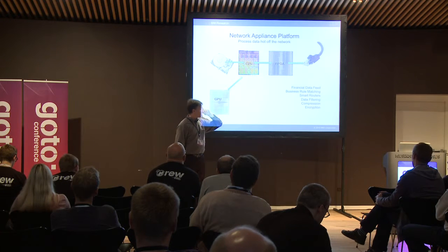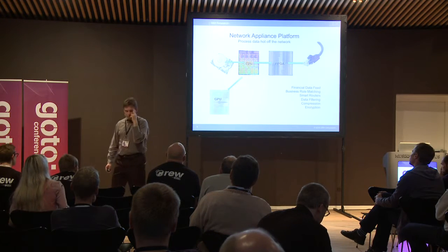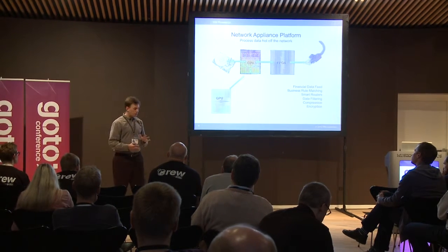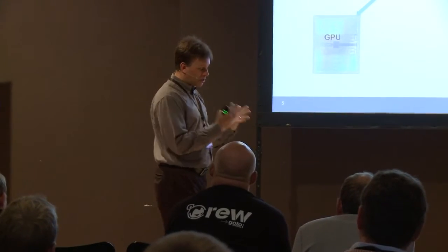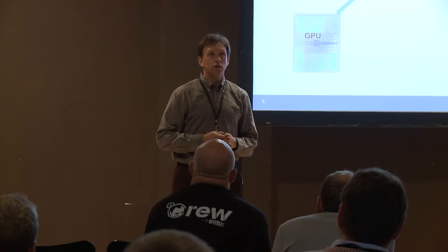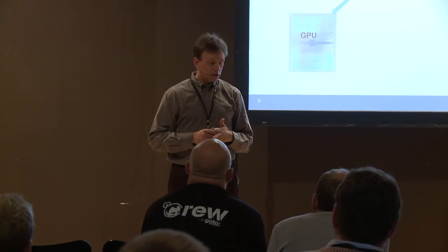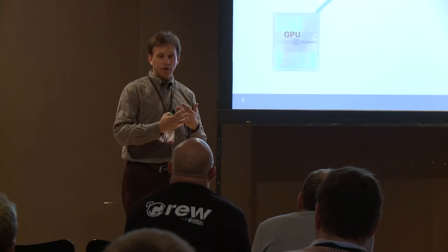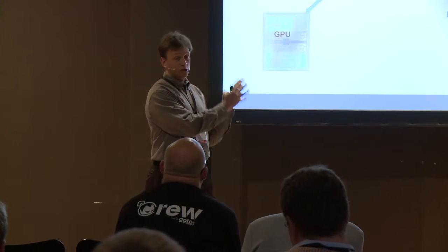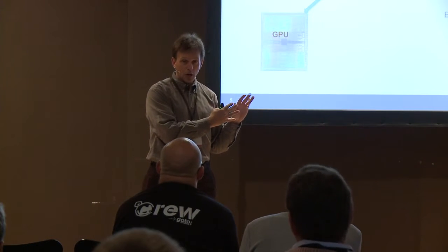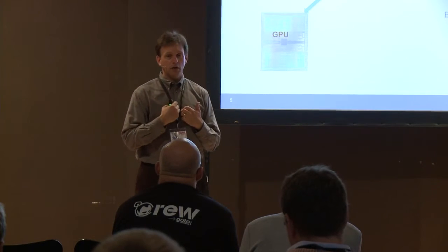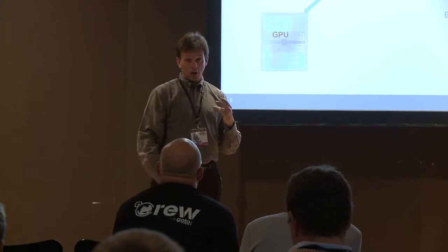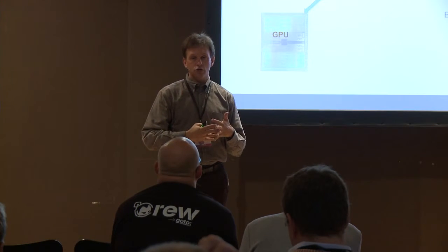Now, gzip is an interesting application. I don't know if you're familiar with the algorithms, but there are static and dynamic versions of the Huffman algorithm. People are doing FPGA compression apps, but the compression algorithms that you generally do in software, which use dynamic Huffman schemes, are more effective with compression, but they're extremely difficult to map to hardware because they use dynamic structures. Yet, this is the kind of code that in theory, well, actually in practice, we can express in our language, and if our compiler is able to implement it well, we can actually use a better algorithm.